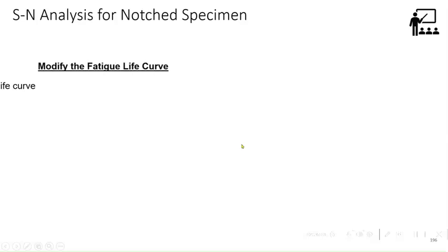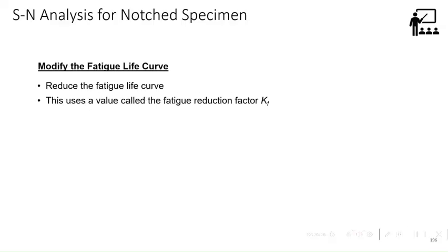So the alternate ways to improve your accuracy, if you are not meeting somewhere, you have to mitigate, then you have to go that way. Again, the way you have generated the SN curve for a smooth specimen is by scaling based on the material properties between the high cycle fatigue range of 10³ and 10⁶. For 10³ it is 90% of ultimate stress, and for 10⁶ it's 50% of ultimate, as long as it's a ferrous